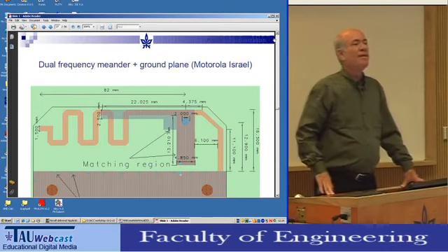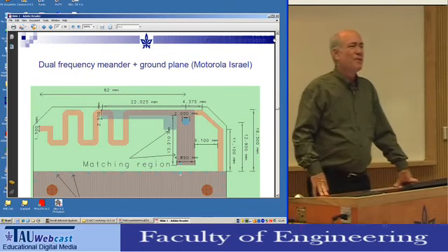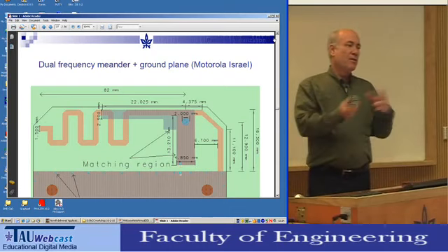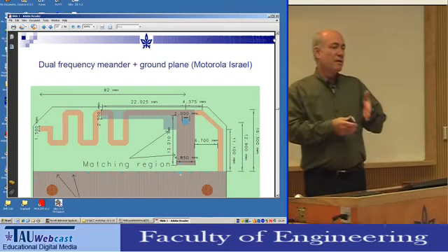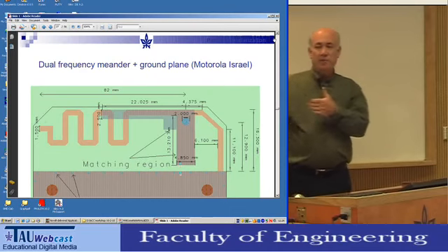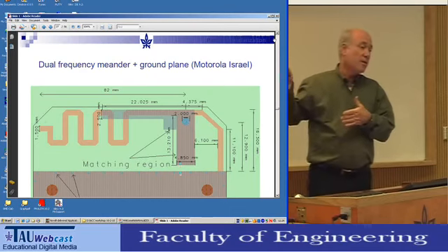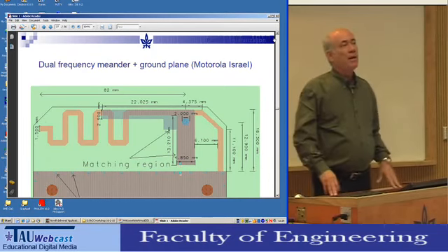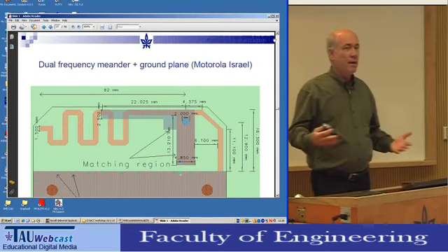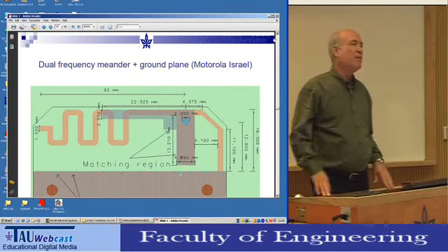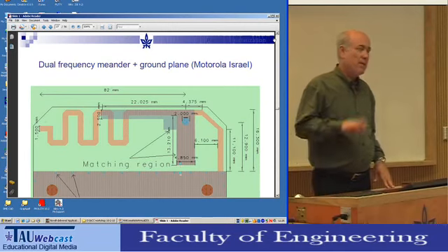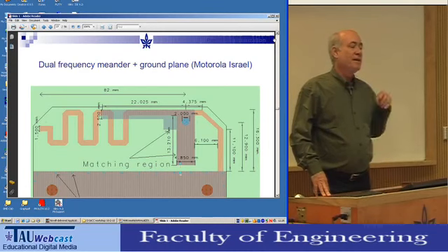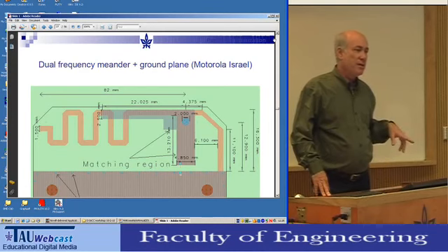Does it work with loop antennas with ferrites inside? Loops are the analog, or the dual, of the wires. You can look at loops like magnetic currents. I was showing an electric current. If you just replace everything by magnetic current, then a loop has about the same performance, the same characteristics. With one reservation: since you are feeding it differently, the impedance behavior close to the origin, close to zero frequency, is even worse.